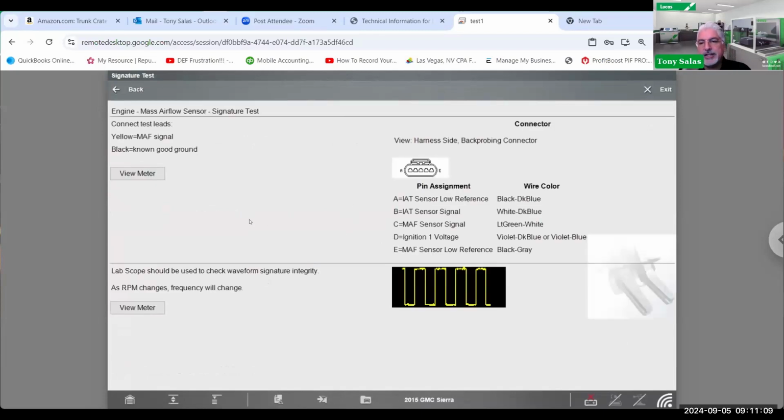So this is live readings again, because you have to understand that you're looking live at the signal to see if the signal is dropping out. So there are two points to be made here. One thing is to look at your scan tool readings of a specific sensor or PID. Another thing is to hook up a meter or a scope to see it live, what the wire is doing at the connector or at the ECM, PCM.